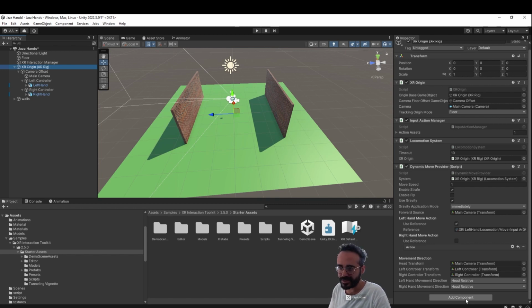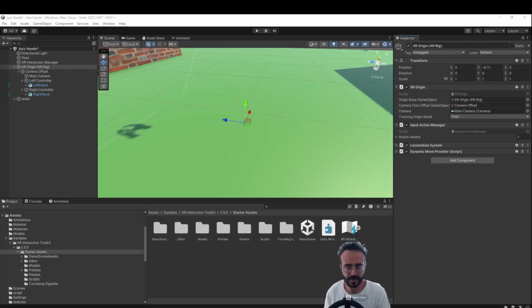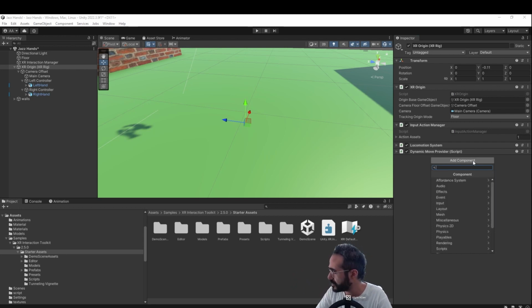We are moving around the camera and the XR rig, but we don't have a body. We want a body. We need a character. We should be a character with physics and so on. So to get the body, we need a character controller that is also used for FPS games and so on, to give some physics to the player being controlled around with the WASD buttons. So let's try to get that character controller.